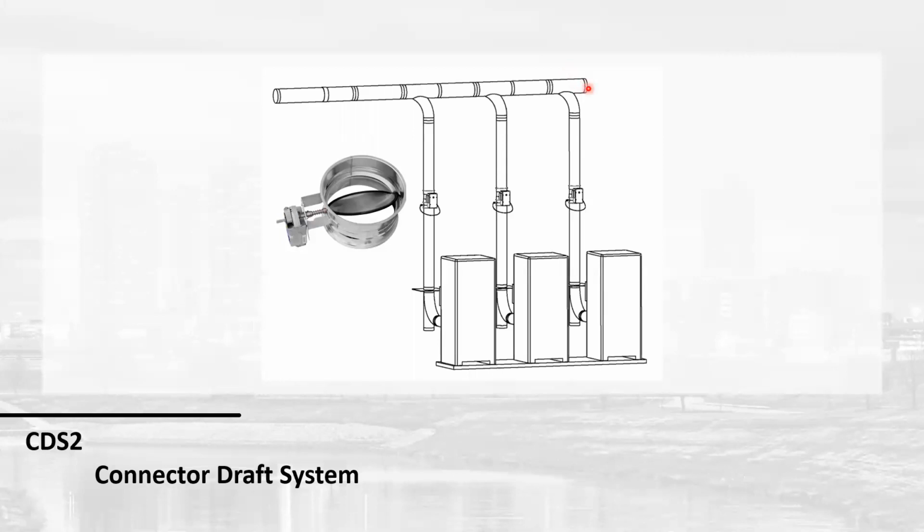This is also great for, again, I talked about that job in Chicago where we had 10 different appliances, 3 different styles. Each of those appliances had a different pressure requirement. The boilers wanted to be slightly negative. They were more of a category 2. They ran really well at about a 0.04, 0.05 negative pressure. The humidifiers ran fantastic at neutral. They wanted to maintain 0. The boilers, they wanted to be a half an inch of positive.